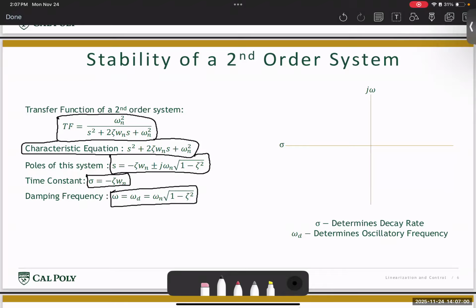And this keeps going on in the feedback loop until 5 degrees in the aircraft is achieved. And we basically have some amount of control over how fast this aircraft settles into this final pitch state of about 5 degrees. And we also have some amount of control in how long the aircraft is going to take in order to achieve this, along with the number of oscillations we're going to see in a system. We're going to dig a little deeper into that in just a second.